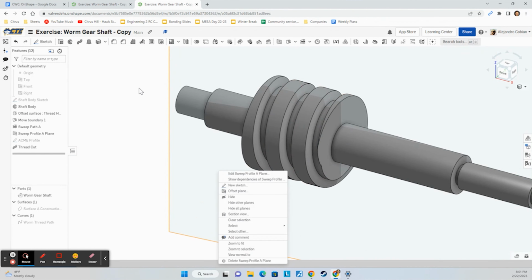So go ahead and click on fillet. Let's select this edge here, and then this edge here. For some of you, your value here for the radius might have a value of 1, and you might have this error. So just go ahead and change this to the value that we need, which is 0.125, and we should be good. So once again, it's 0.125, and hit enter.